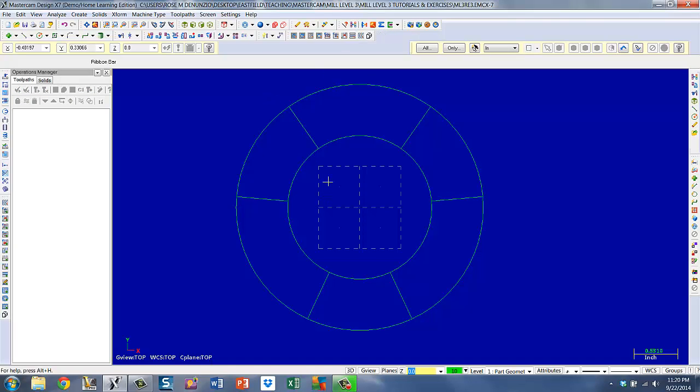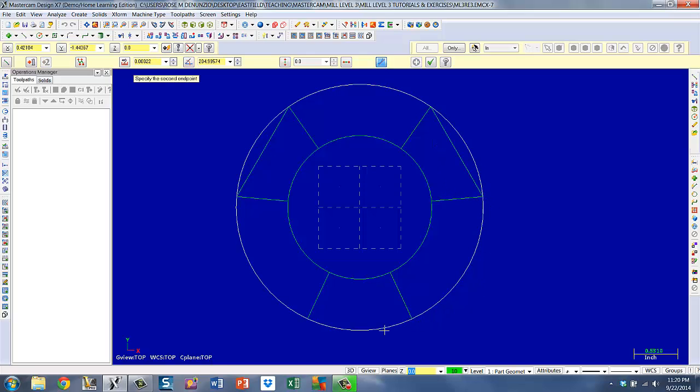Now I have these protrusion sides that look to be tangent to the flats. So I'm going to create some lines at those tangent points. This is basically create line endpoint. I've got a flat from this endpoint to that one, a flat here, and a flat here. And those look good. I'll check out of that.